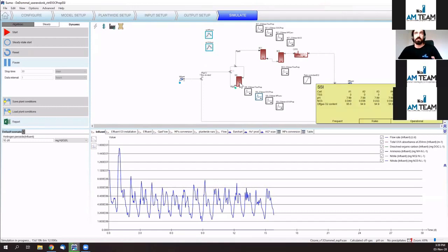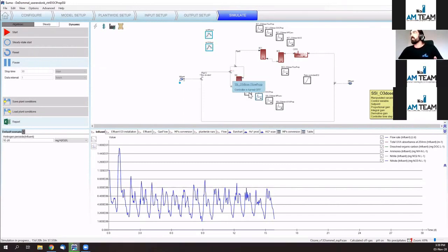side stream injection device. So in here, you have the gas transfer of the side stream injection, which very efficiently injects ozonated gas at a certain concentration, depending on the generator in use, and can be controlled with different control strategies. Here you see different examples of controllers, like a flow proportional controller, DOC proportional control, even micropollutant-based controller, because that's the next step.